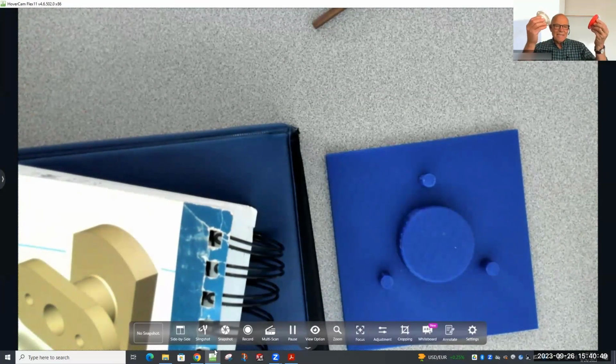I've got two of these now, and they have a bolt hole pattern. A bolt hole pattern is that series of holes that goes in a circular fashion. And although they weren't designed to bolt to each other, they could bolt to each other if the surfaces are flat enough, and if the holes line up well enough, and if the holes are themselves large enough, and if the entire pattern is in the right location. Those are all geometric concerns as opposed to dimensional concerns.